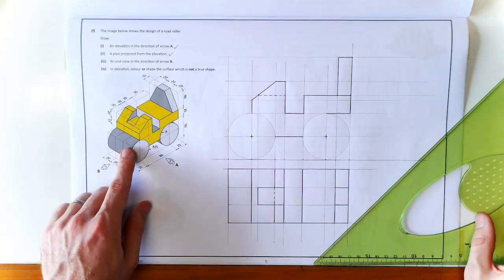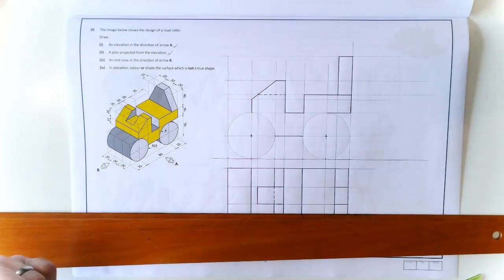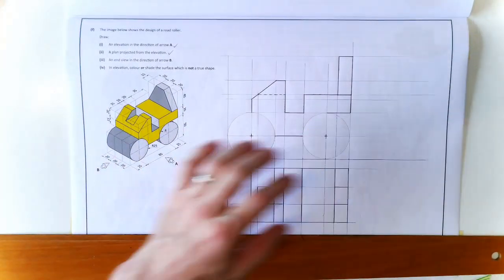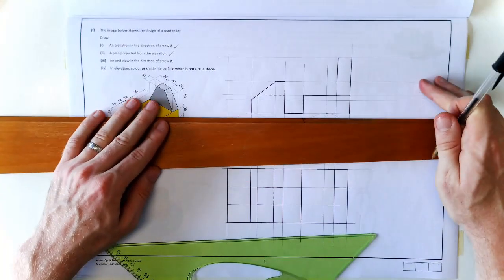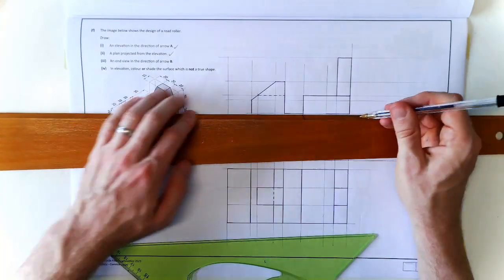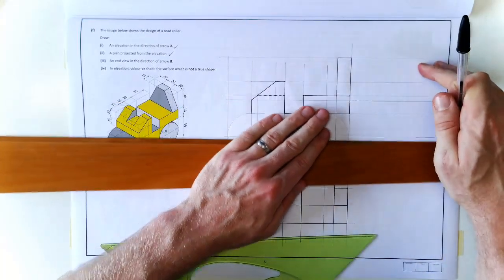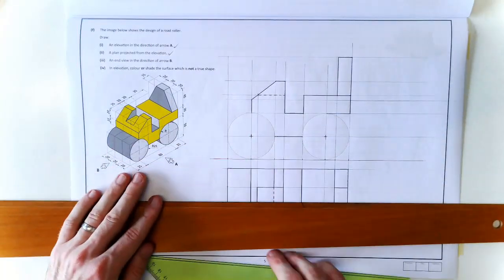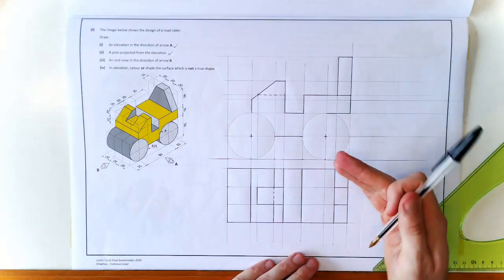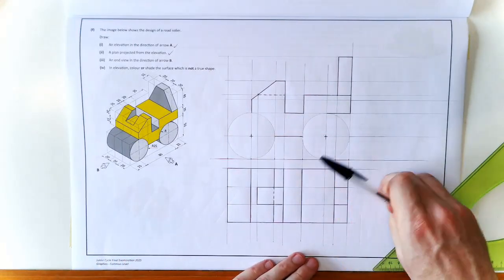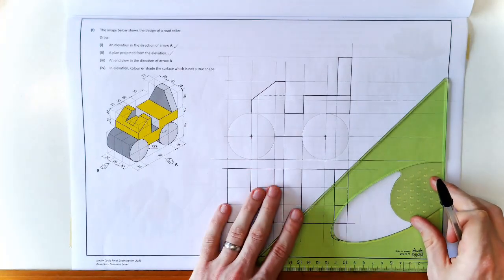Next up then is our end view. So end view, we need heights and we need depth. So height, I haven't got them all taken across, but let's project these across a little bit better, a little bit clearer. That's all my heights. Okay. And then our depth. Okay, two ways. You can either have a 45-degree line, bring them out and straight up, or I like to just take them directly up at 45 degrees.